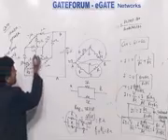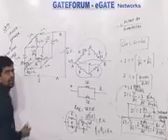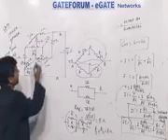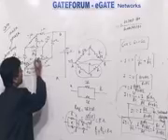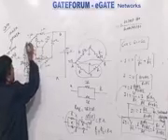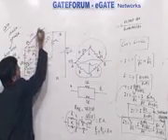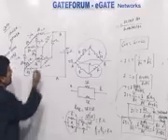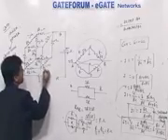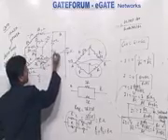This I by 3 will be divided as I by 6, I by 6 in 2 equal branches, because the 2 branches have equal resistors, so the current is divided as a half of the actual current which is flowing up to this point. Then this I by 3 will divide as I by 6, I by 6. I by 6 and I by 6 will become I by 3. Similarly, this I by 3 will be divided as I by 6, I by 6. I by 6 plus I by 6 is nothing but I by 3.